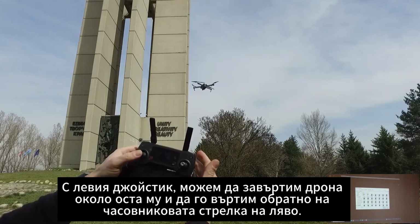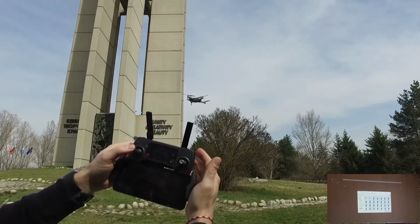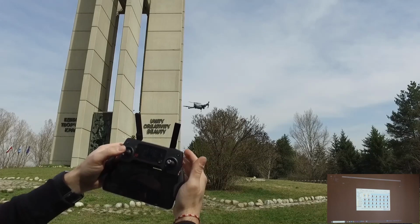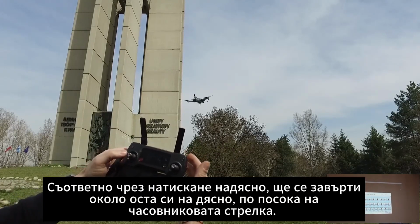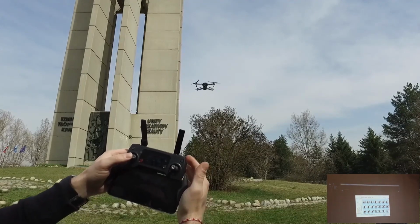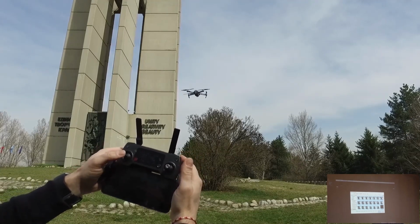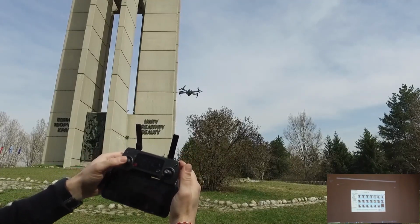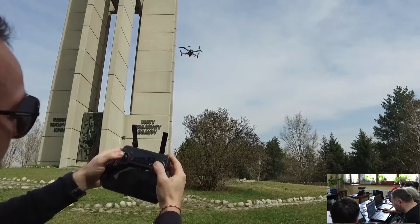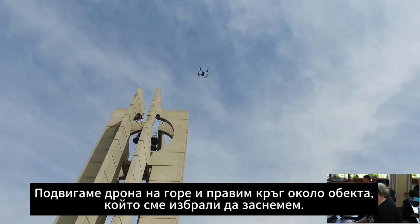With the left joystick we can rotate the drone around its axis; we rotate it counterclockwise to the left. Respectively, by pushing to the right, it will rotate on its axis clockwise. We lift the drone up and make a circle around the object we have chosen to photograph.